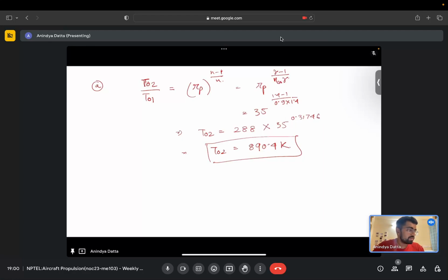Okay, but now we are getting... and then use the definition of isentropic efficiency to compute the final temperature. But now with the definition of polytropic efficiency, we can directly find the temperature ratio. We can directly express the temperature ratio as a function of pressure ratio raised to the power of this factor, which is